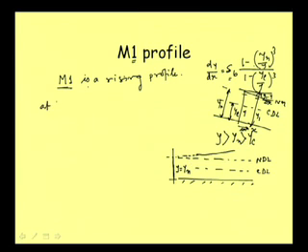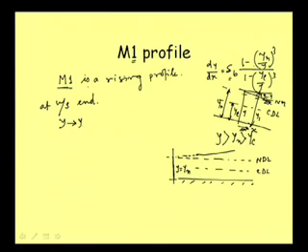So, at the upstream end of the gradually varied flow profile, of course, we should not say that y is exactly equal to yn, because if y is exactly equal to the normal depth yn, then it is a uniform flow. So, we can say y tends to yn, almost equal to yn. Now, if this is the situation, then what will happen to this equation?